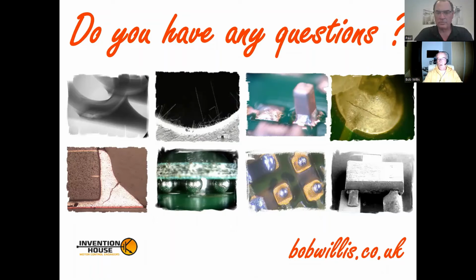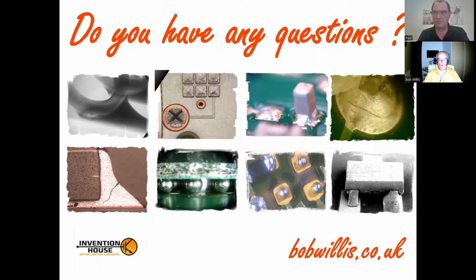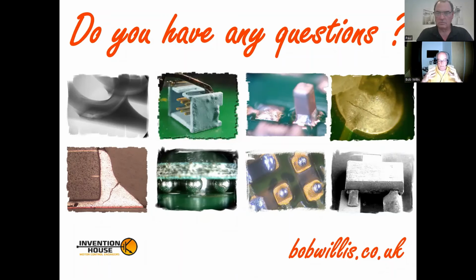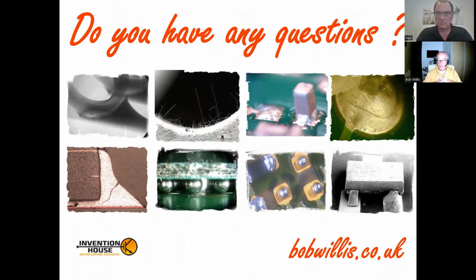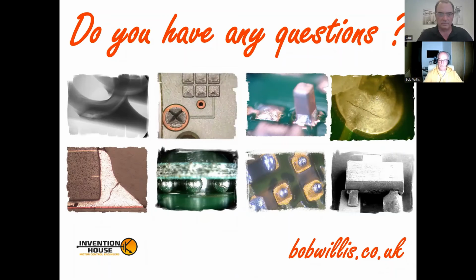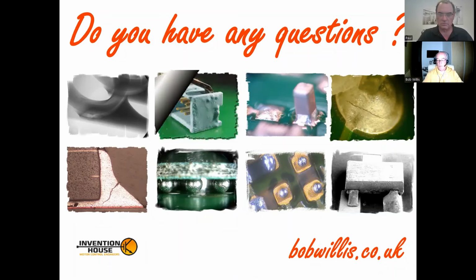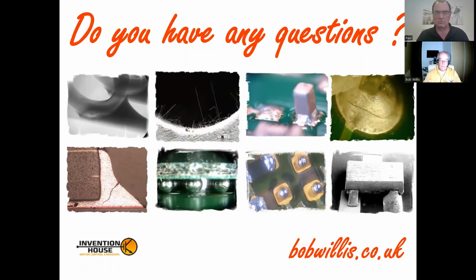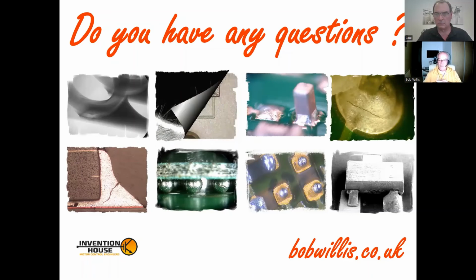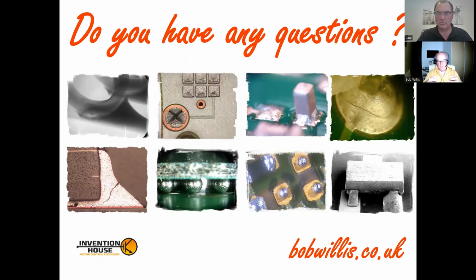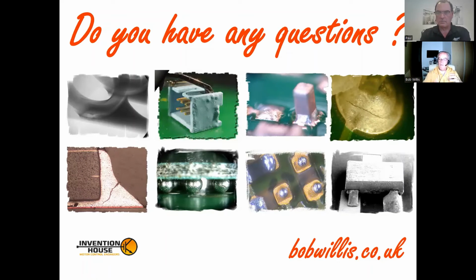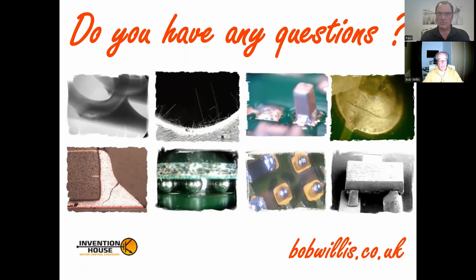The most common question I get is bubbles. What causes bubbles within conformal coating? If you think about it, what's in the bubble? Most times it's air. If you put too thick a coating on, then the air has not escaped from wherever you put it over. If you then put another coating on, as some companies will do with spray coating to build up the thickness, that bubble can't escape. I haven't shown my bubble creation in this particular webinar; perhaps we can do that in a future webinar. If you put a thickness on, you've got to make sure the bubbles will escape, that the volatile material is escaping, because if you put a secondary coating on top to build up the thickness, you won't get rid of those bubbles.